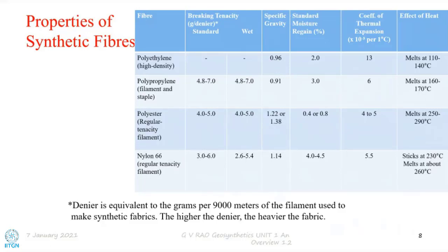Also, when the density or specific gravity is less, that means for a given weight or given mass of material, we are going to get more area. Remember this, isn't it? So a given square meter of area will require more polyester by weight. That is, the quantity of the polyester is going to be more. That means that's why they are going to be slightly more expensive.